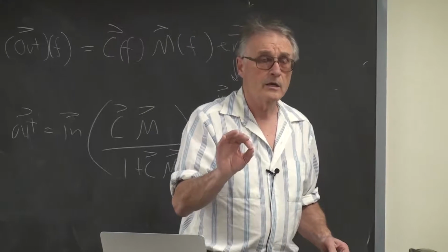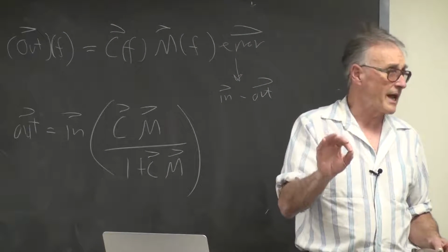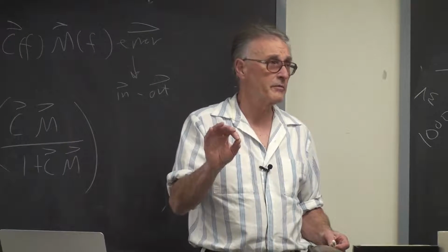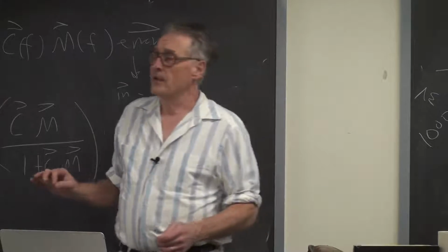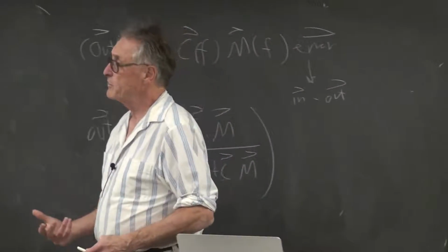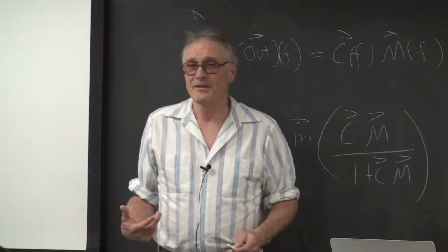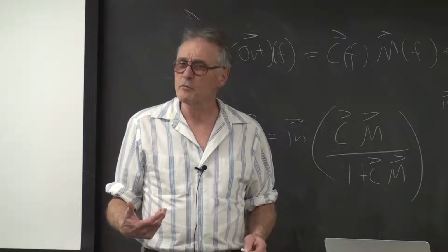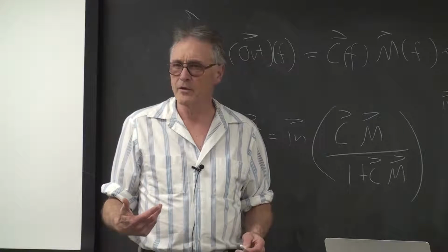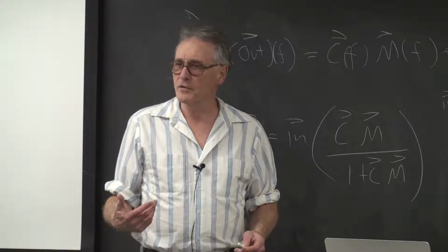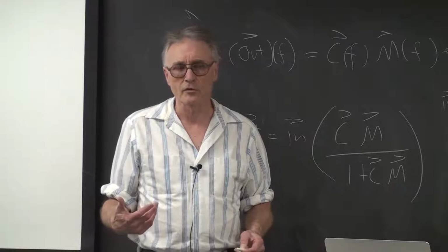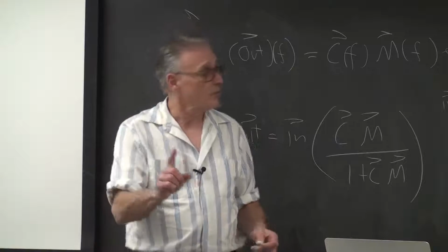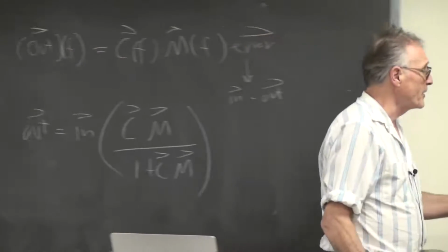You have a time delay. Your last estimate is obsolete as soon as it happens. Your last speed estimate is obsolete while you're trying to run the control loop. And that induces an effective phase shift which is speed dependent. The interesting thing is the system becomes more stable as it goes faster because you're making more measurements per second. And therefore the effective phase shift due to the time delay is smaller. That's one reason we're testing you above 500 RPM.